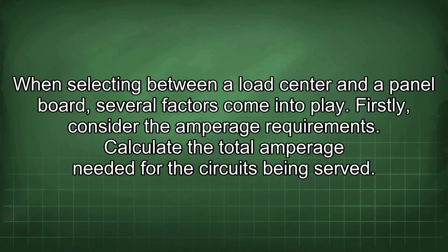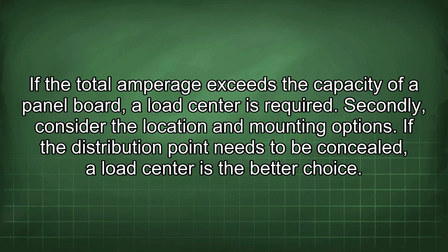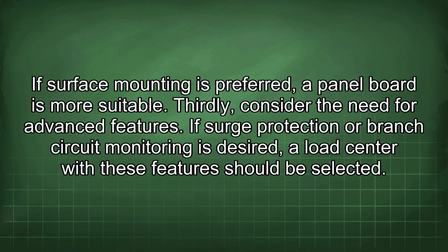When selecting between a load center and a panel board, several factors come into play. Firstly, consider the amperage requirements. Calculate the total amperage needed for the circuits being served. If the total amperage exceeds the capacity of a panel board, a load center is required. Secondly, consider the location and mounting options. If the distribution point needs to be concealed, a load center is the better choice. If surface mounting is preferred, a panel board is more suitable.